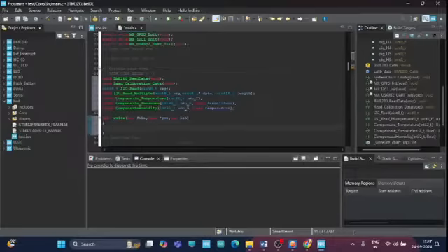So inside what I am going to do is HAL_UART_Transmit, huart2, uint8_t pointer comma len. So here we need to provide that pointer over here. Okay, len, and then HAL_MAX_DELAY, and then return that len.